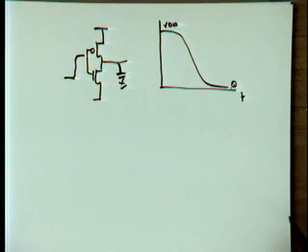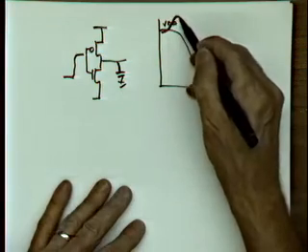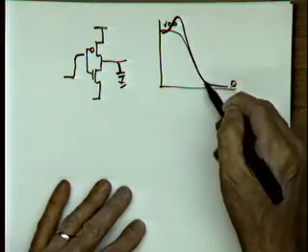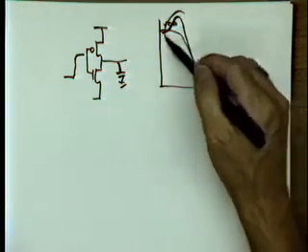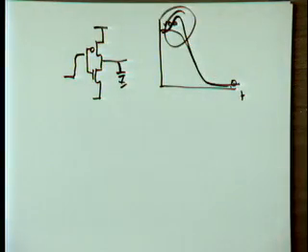Now you put this in SPICE, what do you get? You get something like this, right? So why is that? Why do I get this hump here? What's the reason for that? Well, this is something we call feed-through.